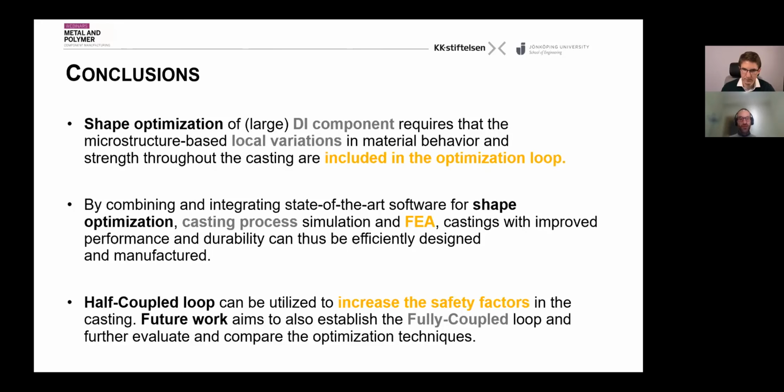And of course, we demonstrated that coupling the casting technology with the stress analysis from the beginning of the study can give us a better result in terms of safety factor, stress reduction, and cost reduction, because I can get lighter castings while respecting all the requirements for the structural analysis.